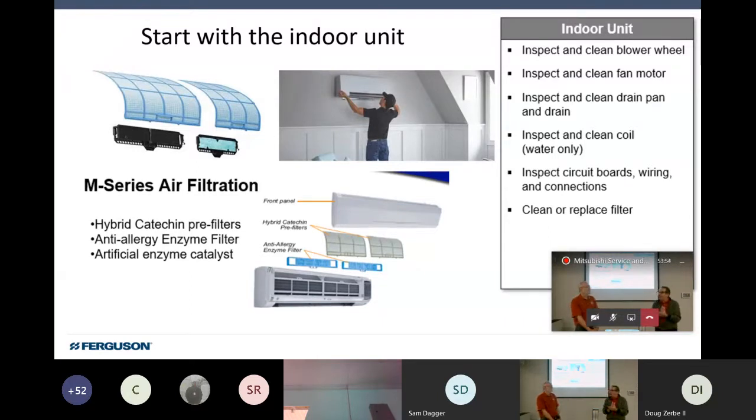So all of a sudden you do maintenance, and a few days later the people call you back that they're getting spitting coming off the coil. You're watching these little bits of droplets or moisture being blown off the coil. And it's like, it didn't do this 2 weeks ago before I cleaned this. Okay, did you use cleaner? Oh yeah, I did. Yeah, and that causes it.